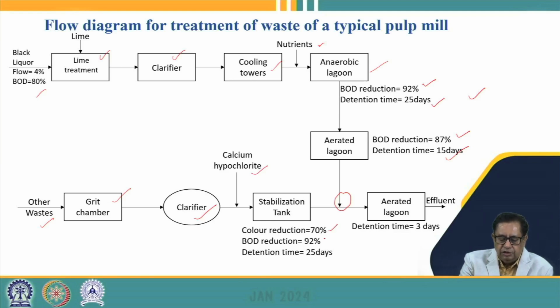It can result in the BOD reduction of 92%, and we provide a retention time of 25 days in the stabilization tank for this reaction to happen. After which the wastewater which is generated is mixed with the wastewater coming from the treatment of the black liquor, and then it is taken to an aerated lagoon where we provide a retention time of 3 days, and then we can meet the effluent quality standards.